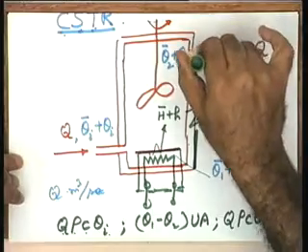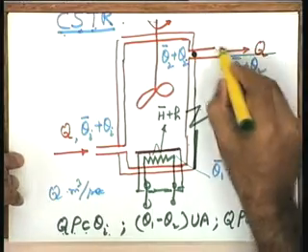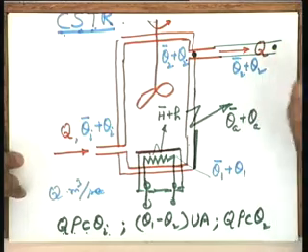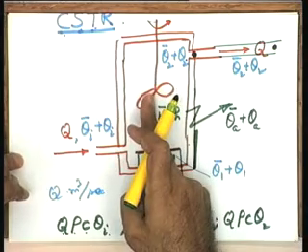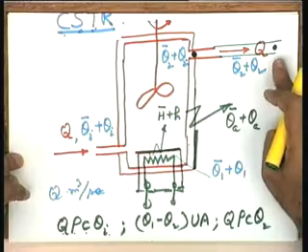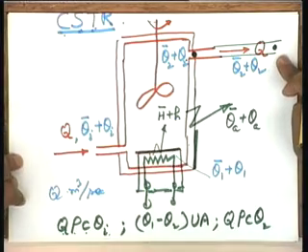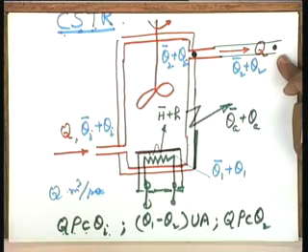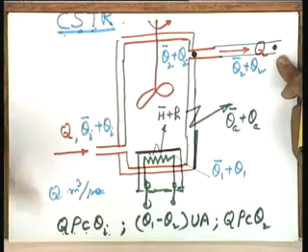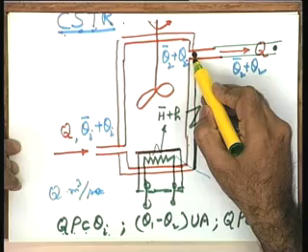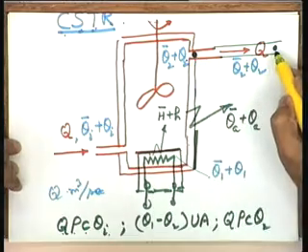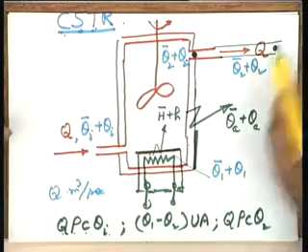alternatives? One alternative, one way is this, that instead of installing the sensor over here, you install this particular sensor a little away, let us say at this particular point, so that the effect of thermal agitation, so that the effect of vibrations is reduced, if not eliminated completely. Electrical filters of course can be used, but why first create noise and then filter it? It is better first to avoid noise signal right in the beginning, and to avoid noise signal, the sensor instead of this particular point may be put at this particular point, and this is what is normally happening in the process